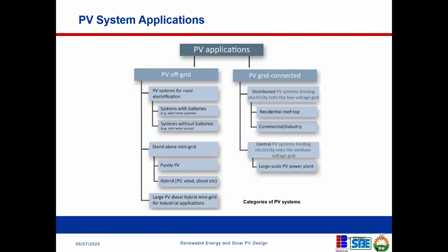So we log for several months. We see the peak demand on that log, we see the availability of the grid, and we see the outages. We feed this information to HOMER. HOMER then fills those outages with the solar PV system and generators, depending on the one that has the least levelized cost at every point in time, whether in the morning, afternoon, or night.